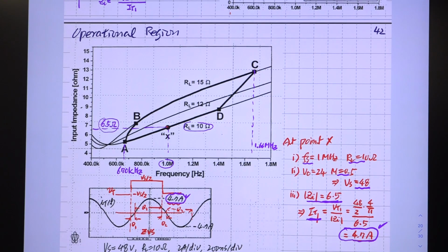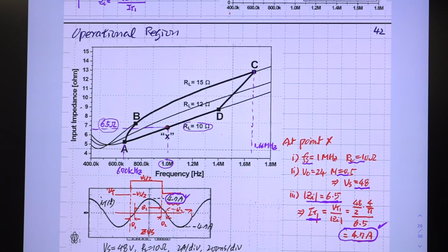Somehow this prediction of the fundamental frequency model, in every analysis here, we implicitly assume that the voltage waveform and current waveform are purely sinusoidal. That's called the sinusoidal approximation. Initially we assume that, and all the analysis and design people, everybody is assuming everything is sinusoidal. That is the fundamental approximation. Without that approximation, it's extremely complicated to predict anything about this. Okay? So this is good, right?